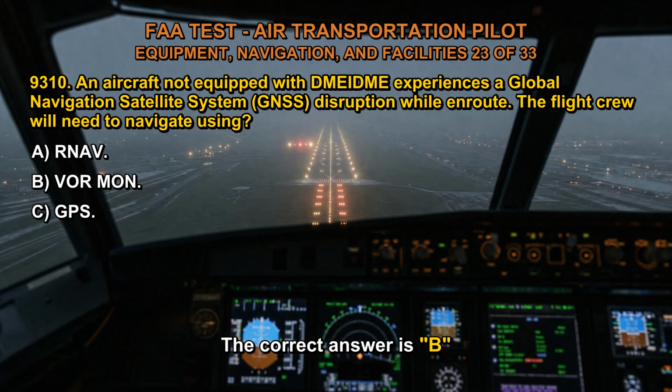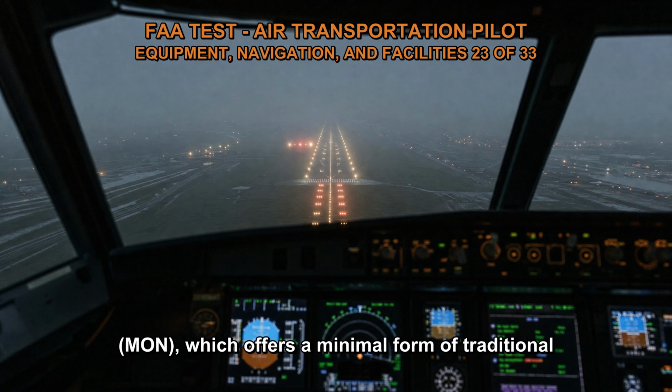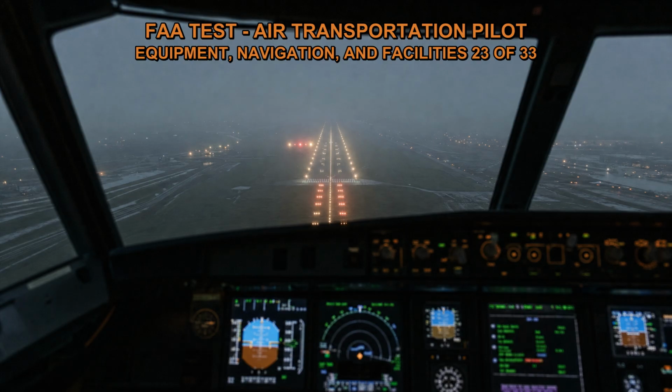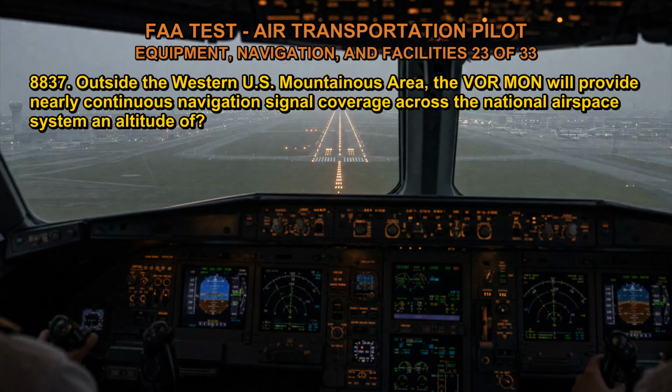The correct answer is B. Operators can utilize the VOR Minimum Operational Network, MON, which offers a minimal form of traditional navigation in the event that GNSS is rendered inoperable. In the event of a GNSS outage, the MON will allow aircraft to safely land at a MON airport or navigate through the afflicted region.